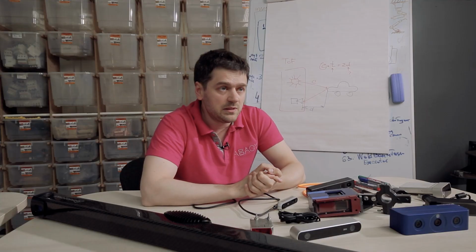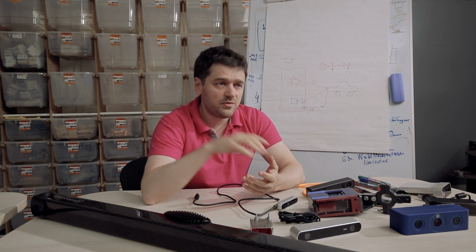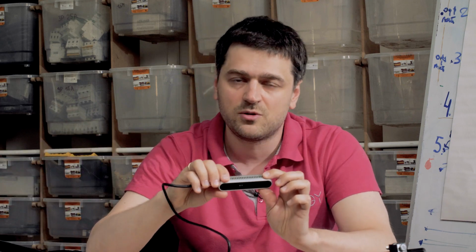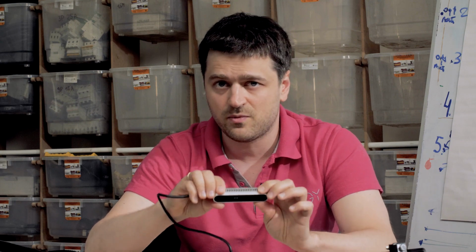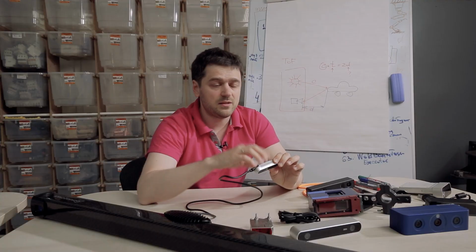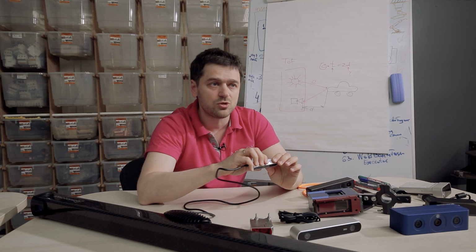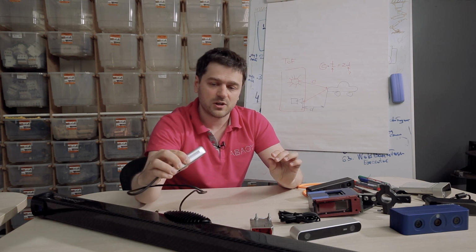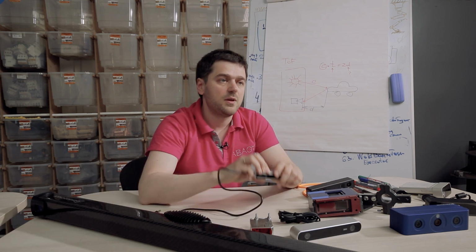As for the shooting speed, sometimes if the scanner is mounted on the robot, you want to scan really fast and move the robot really fast, and it requires the camera to be able to shoot at a high frame rate per second. And in some cases you don't need to shoot while moving, and you can take a shot, move, take a shot, move, and so on.